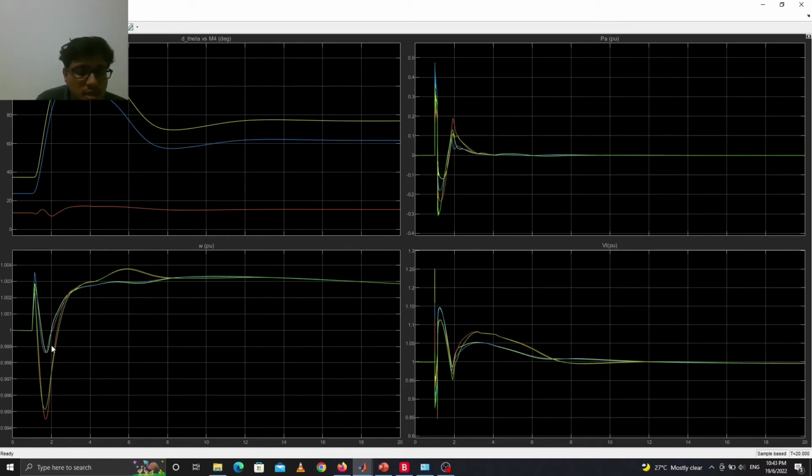at the end and the load change at the bus 9, and then it represents the normal condition of the model system prior to the sudden load decrement at the bus 9 at the time 6 seconds, and showing that the waveform is stable at the 8 second and above. So the load decrement happened at the bus 9 at time 2 seconds, and showing that the waveform was stable after 8 seconds and above.